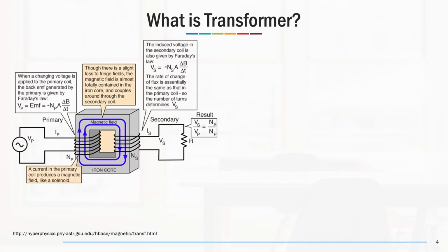So how is the working principle of one transformer? When we have a core with some windings, and we send a variable current to that core with a lot of windings, it produces flux. If we have another winding, that flux can be received by the secondary. If we don't have any core, we will have very high losses.